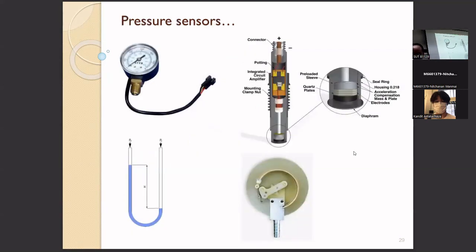This is some pressure, right? Some pressure gauge. And also be careful when you read the pressure gauge. When we use this data to find some property, to calculate some property, it is necessary to check whether this is absolute pressure or not. Because this is gauge pressure. If you would like to check the property of water, the property of some chemical in the standard, it is represented in terms of absolute pressure. When you calculate, you have to convert gauge pressure to absolute pressure.